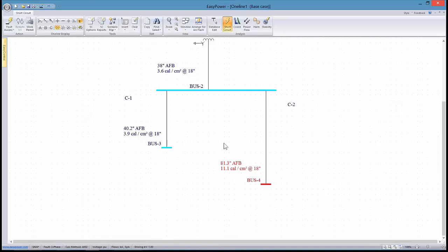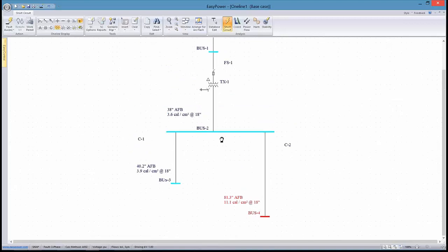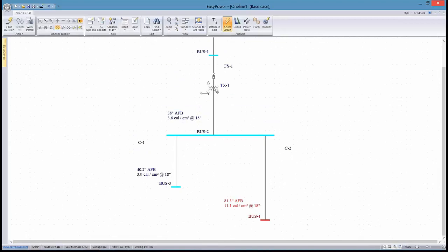Whereas if we go the other 950 feet, the arc flash boundary has doubled and the incident energy has almost tripled. And so this electrician and I both started scratching our heads because we knew that there's only one energy source in the system, and it's a transformer. The farther away you get from that energy source, the lower your energy ought to be. And so his assertion was there's a problem with the software. Well, it turns out this is where the tools come to great advantage.